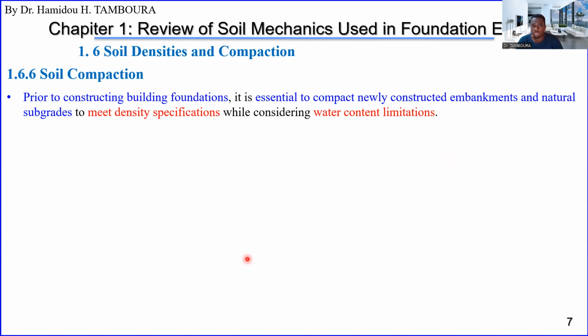So before the construction of any foundation, for example a building foundation, it's very important to compact the newly constructed embankment and natural subgrade so that it can meet a specification, some very important specification considering the water content limitation.